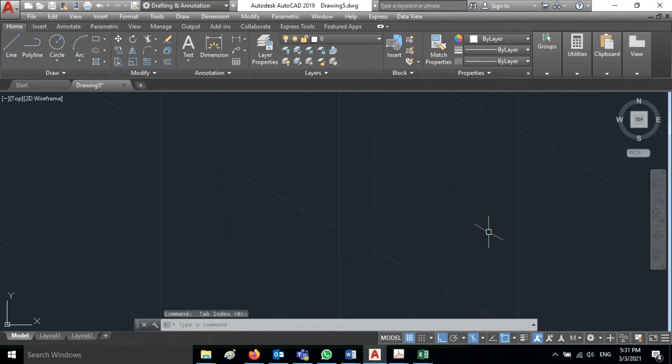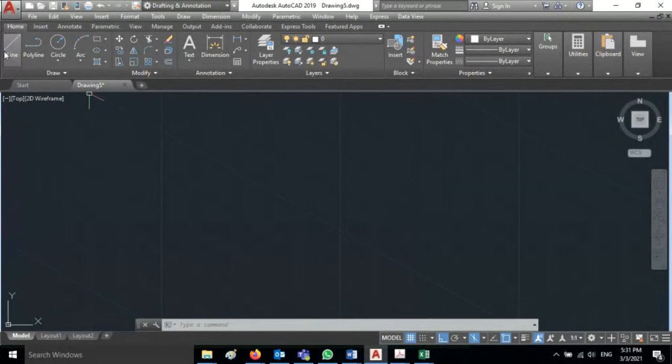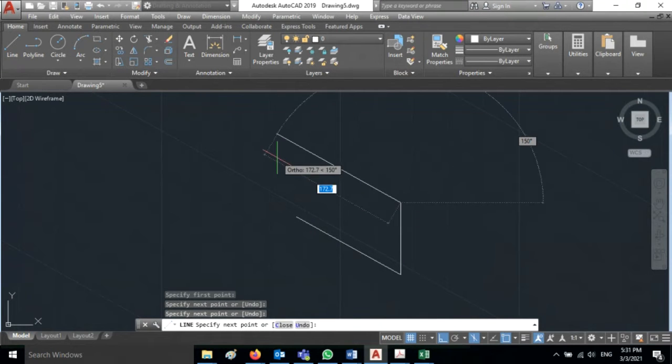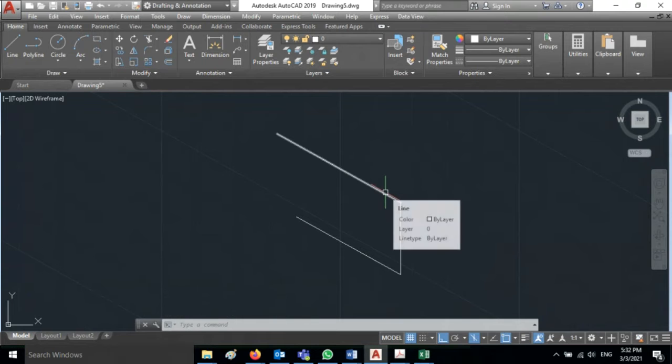And you can see now the squares are now inclined. It looks like isometric squares. Now if you draw any line, let us say if I draw any line, you can see either it will be vertical or inclined. All this angle will be 30 degree inclination. This angle is 30 degree from the horizontal. This is vertical line. This is also 30 degree from horizontal. Therefore we can see the angle.